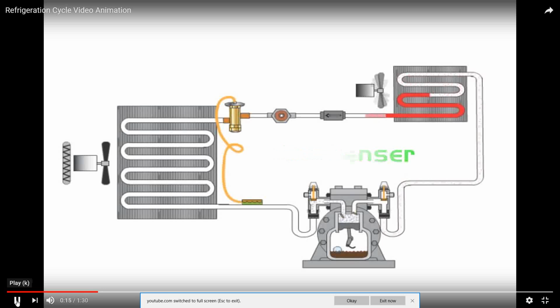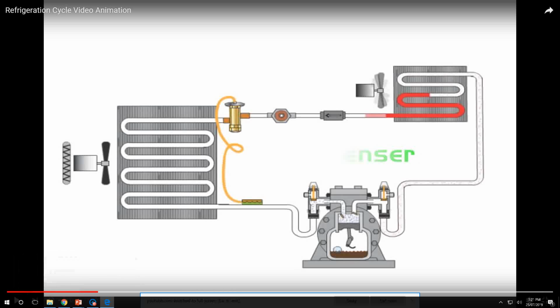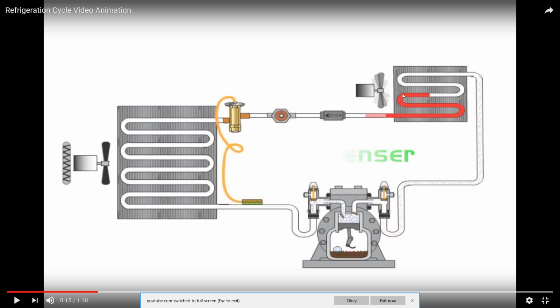In the condenser, when we say condensation, it is a phase change. The phase change is from vapor to liquid, but there is no temperature change. So whatever temperature you're coming in with, ideally the same temperature comes out. There is only phase change. You will have the same temperature and also the same pressure, because the friction inside would be really negligible. So we would say temperature the same, pressure the same. It's just that the vapor has changed into a liquid phase and continues in this cycle.